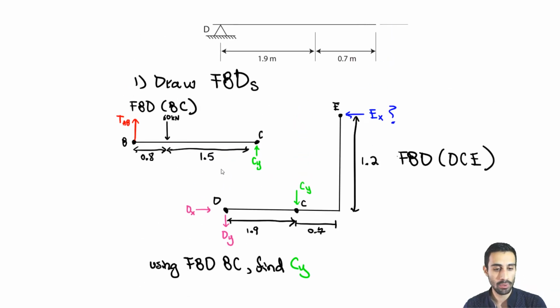So now let's go force by force with their respective perpendicular distances. You have the tension in AB. Does that cause a moment about B? No, it does not, because the line of action hits B. It causes no moment. Next one, the 60 kilonewtons. That 60 kilonewtons hits this point. To get a moment, you have to have a force times perpendicular distance.